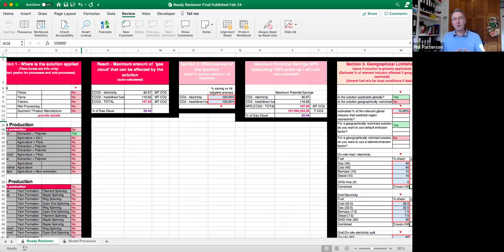So if, for example, you have got a process which is looking at delivering savings for reactive dyeing of cotton on jet dyeing machines, we've got a 10 bath model process in there with 3 baths for preparation, a dye bath and 6 wash-up baths. We want you to use that to compare your solution. So if you are saying that you are saving 2 wash baths, but you've got a model process of a 3 wash off, then you're going to have much higher savings in your calculations. We want you to recalculate using those model processes.